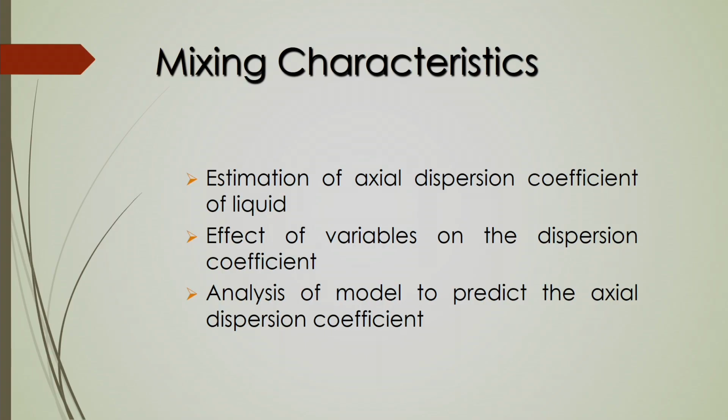Next, another important hydrodynamic characteristic is called mixing characteristics. In that case, what will be the degree of gas liquid mixing or gas liquid solid mixing inside the column is very important, because this mixing characteristics will give you what will be the performance of that particular mass transfer or heat transfer for the particular chemical engineering operation.